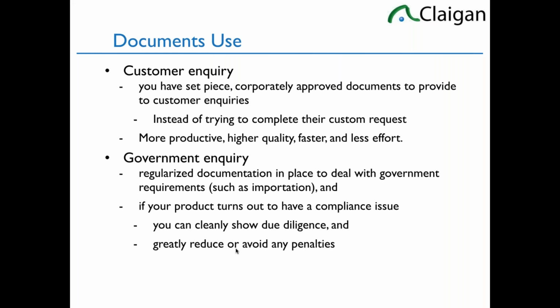And the other thing about core documents, it's not perfect. There are gaps. It does have high coverage, but at least it can show due diligence when you make a mistake. By the way, there's going to be tons of mistakes in there. If you have a product, ignoring the circuit board, with more than 1,000 parts, it's not going to be compliant for RoHS most days. The rate of human error we're seeing once you get to higher part counts is such a large influence. You're going to have non-compliant products all the time.